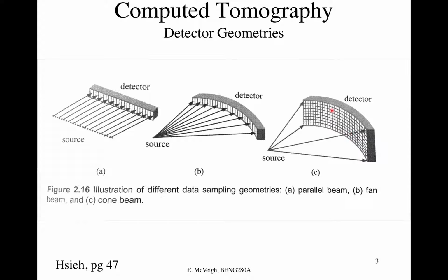The way these things are designed right now, 99% of CT scanners sitting in hospitals have a separation between these pixel elements, or sometimes they're called detector elements or dexels as opposed to pixels, of usually about a millimeter, plus or minus 10%, right?